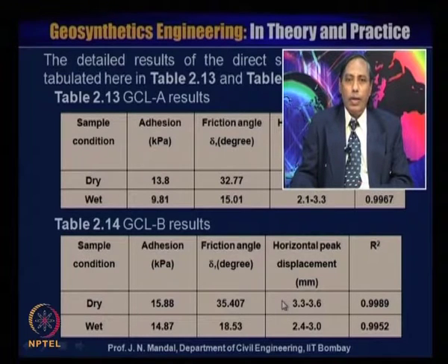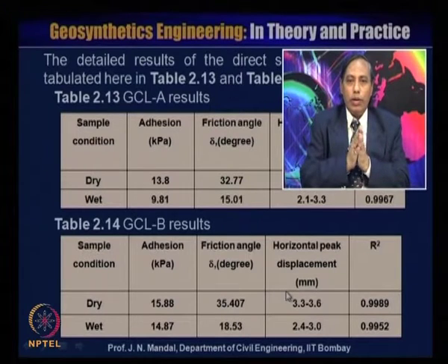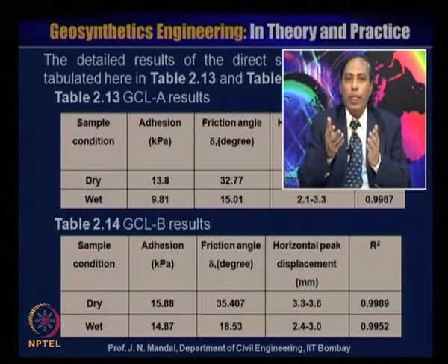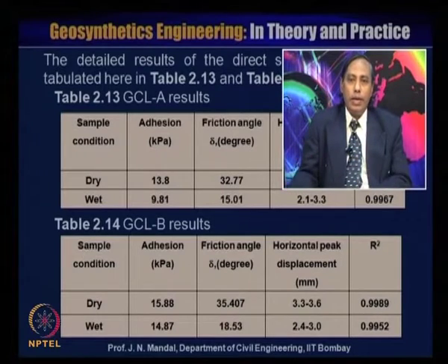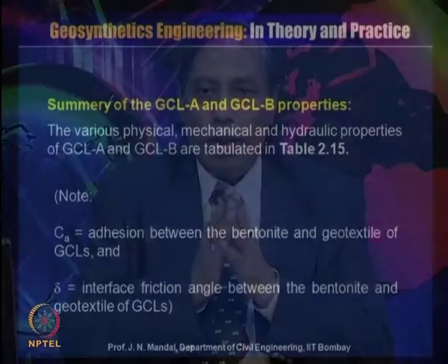So, in all cases, whether the geosynthetic clay liner is in the dry condition or the wet condition, in most cases the adhesion value is higher in the dry condition with respect to the wet condition. Both the adhesion and the friction angle are higher, but the horizontal peak displacement is not significantly different.